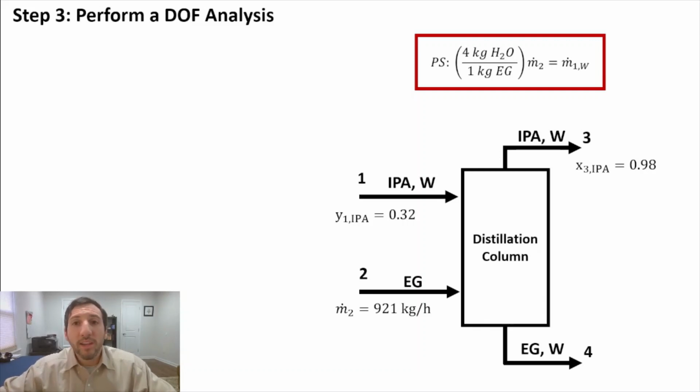And so now we're looking for our ISVs. Counting our independent stream variables, we see that it's going to be 7. The way we get that 7 is that we've got 2 components in stream 1, 1 component in stream 2, and then 2 components in both stream 3 and 4. When you sum those all up, that gives us 7 ISVs.